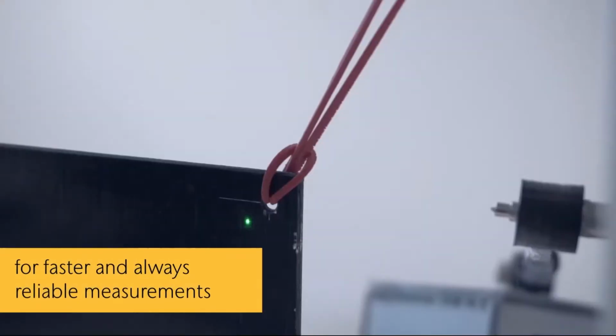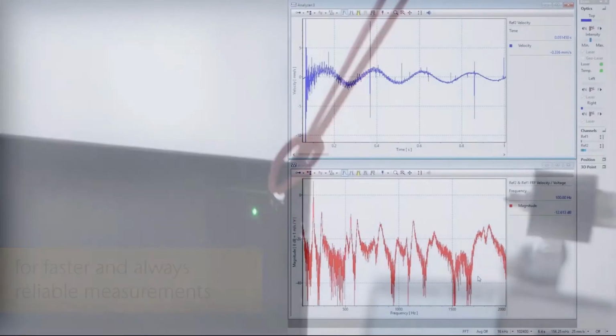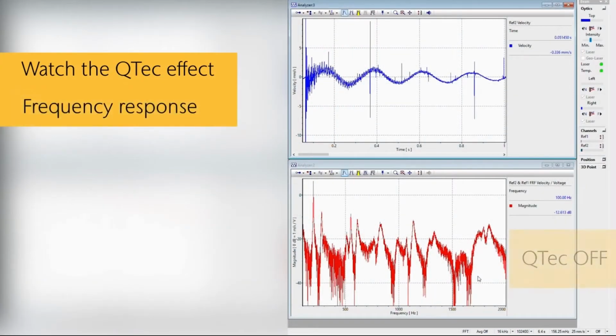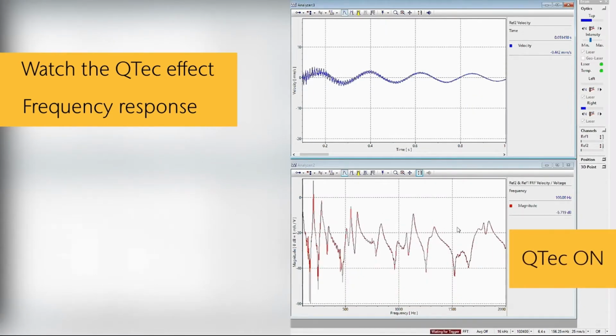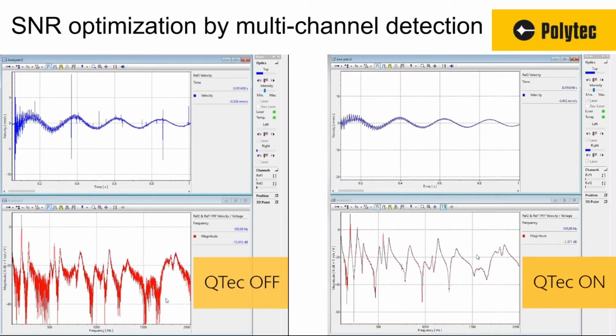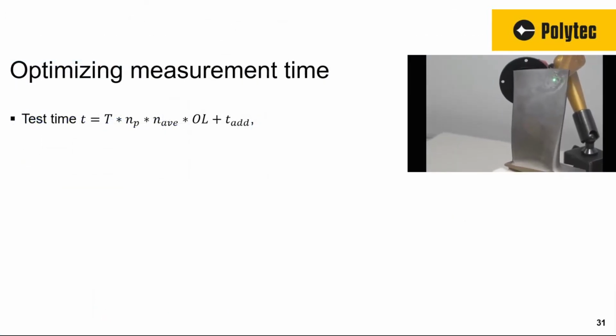And the effect is a higher optical sensitivity and a better signal to noise ratio, which we'll see in the measurements. So if you switch QTAC on, the noise is dramatically lower. Now we can compare again both graphs. And with the elimination of the surface effect, the noise is gone. Now we have optimized the signal to noise ratio by different means.